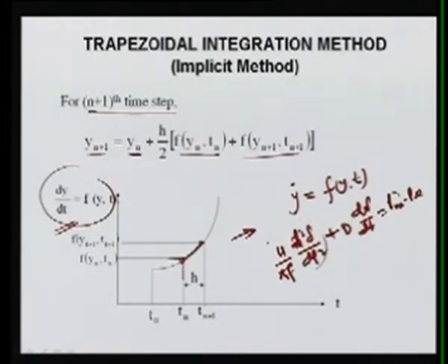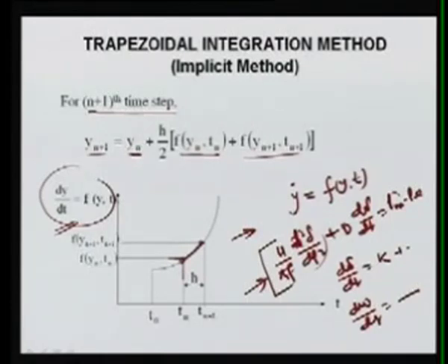So what we can do is write this double differentiation term as two sets of differential equations: we can write d delta by dt as some function of delta, and we can write d omega by dt as another function. Because d delta upon dt is nothing but your speed.